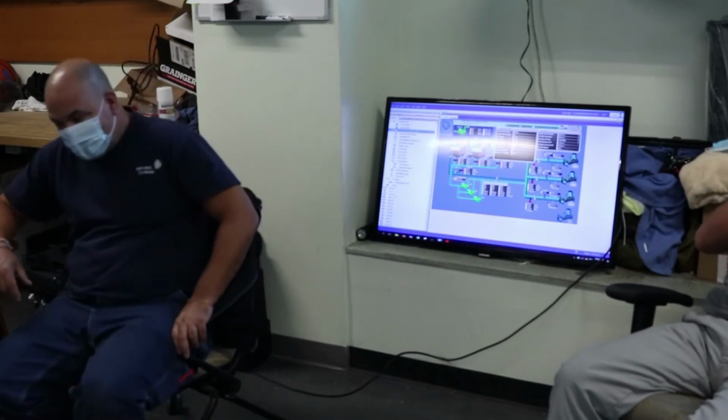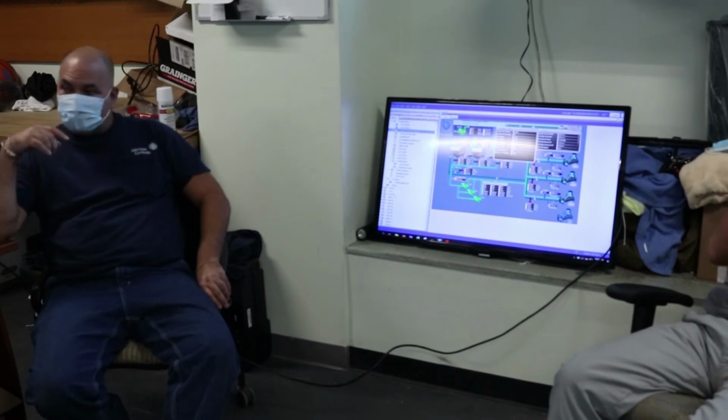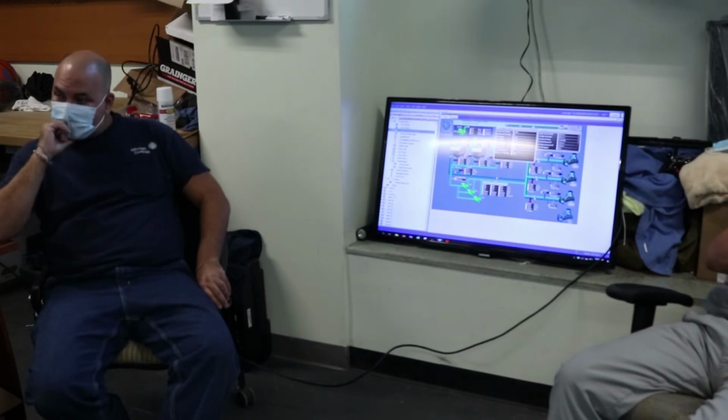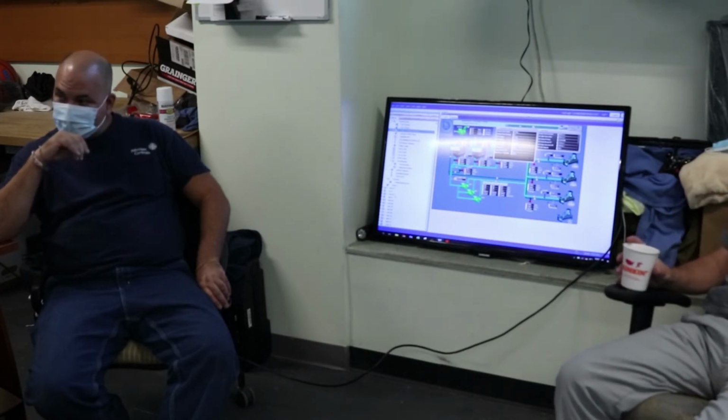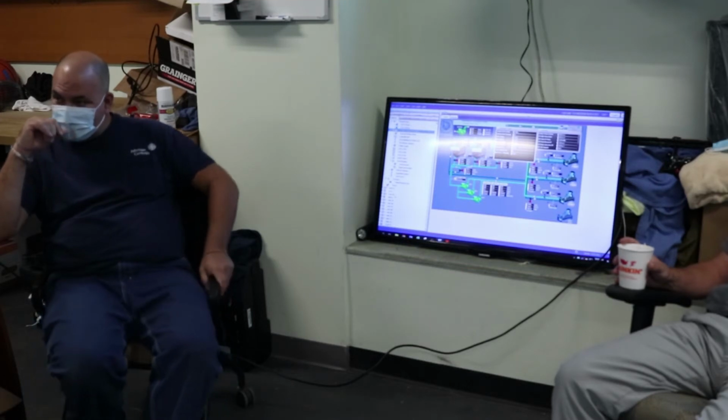Then you've got a water heater in 14. Correct, but that's the problem in 11. You already have one of those high efficiency units, and there's no way to vent it. They put it in the same mechanical room. What they needed to do was put it in the boiler room, where there was a straight shot up through the roof, and pipe it to the mechanical room. Because now they can't vent it. It would have been so much easier. But we ran out of room in the mechanical room. I kind of get where their head was at. But how much more electric can we squeeze in there?